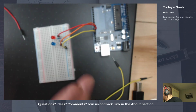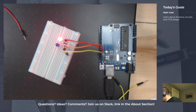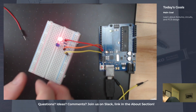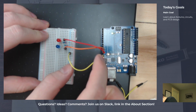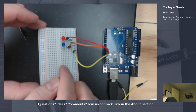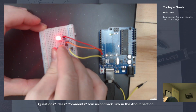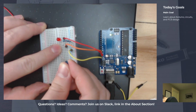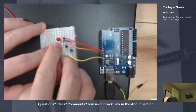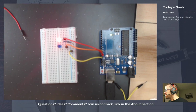And now we've cleaned things up, and we've condensed it down so we can plug more things into our circuit. So much less space, so much cleaner. Looks like I didn't wire up this LED properly, so let's see what I did. The orange line comes into one side of the LED. Interesting. The other side goes to the resistor. So I should be able to plug that in. Okay, it looks like I just had a loose connection, so I pushed things down in, and we are good to go.